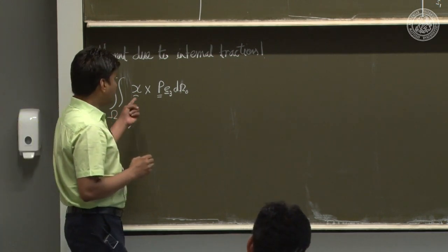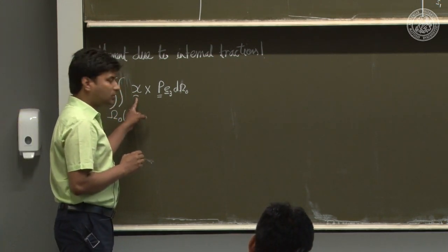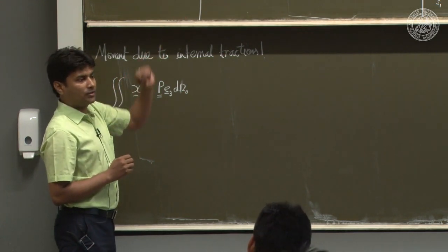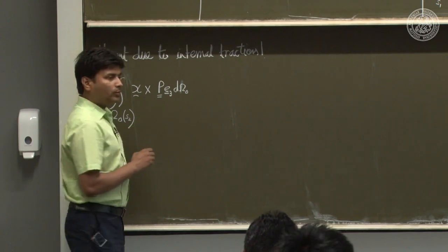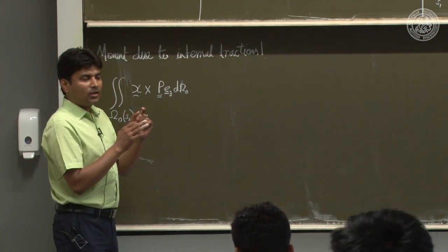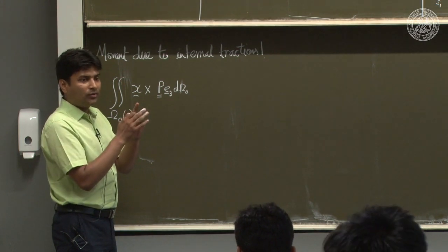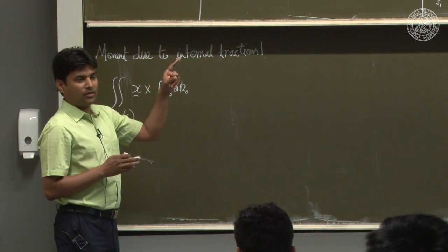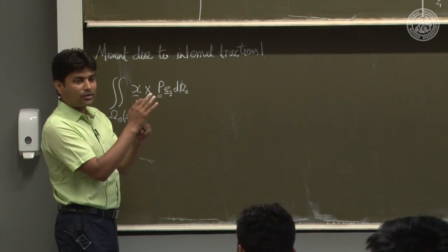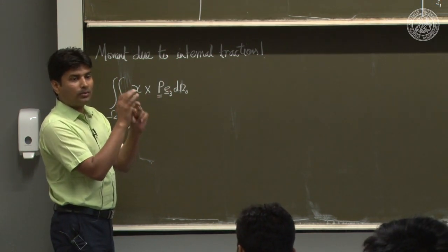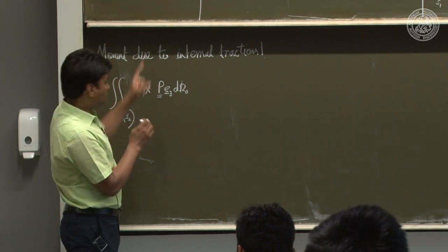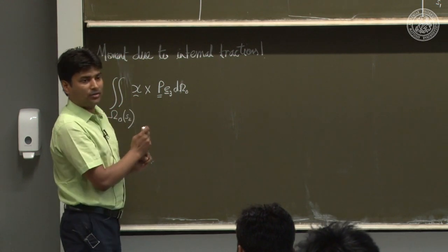And again we want to split it into two parts. This little x I want to split into two parts as we have done earlier, because in beam theory all the forces and moments in a cross section are about the center line. When we say moment at a cross section in a beam, that is moment about the center of the cross section, not about the origin. So therefore, we have to do that splitting here.